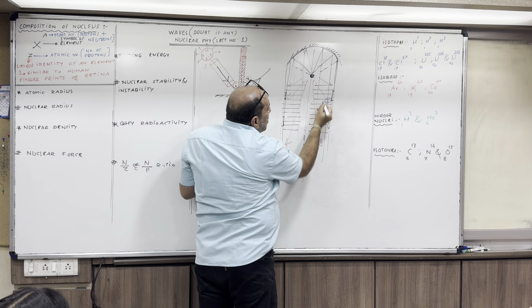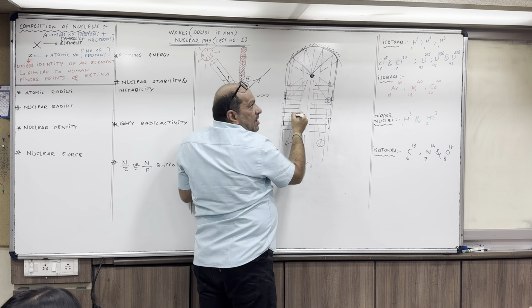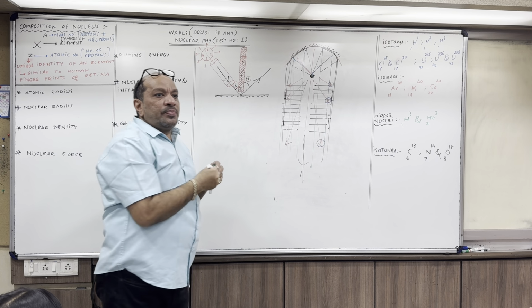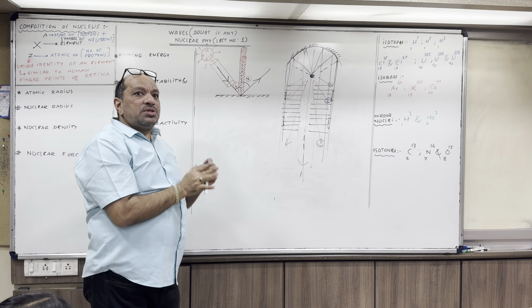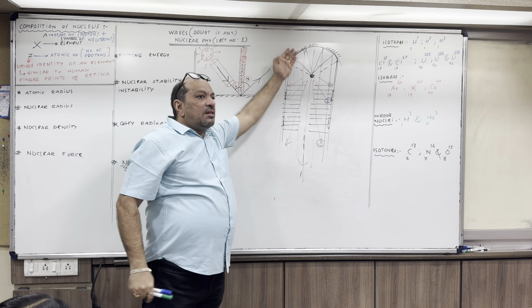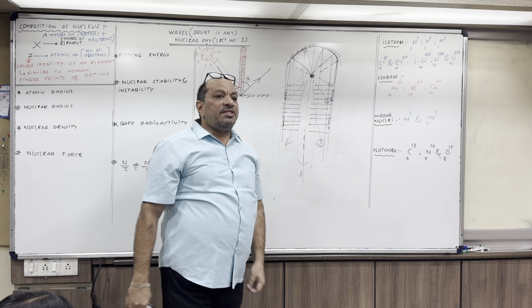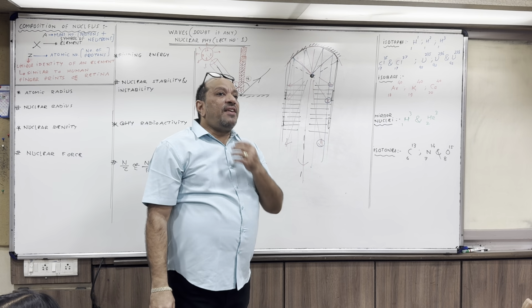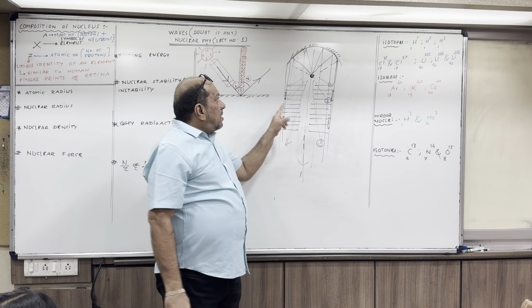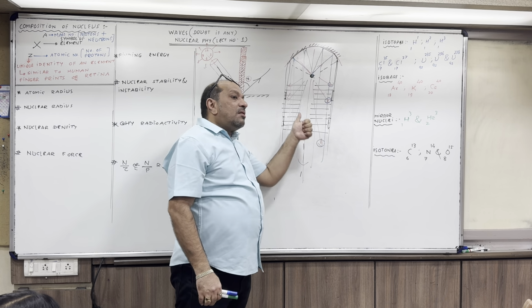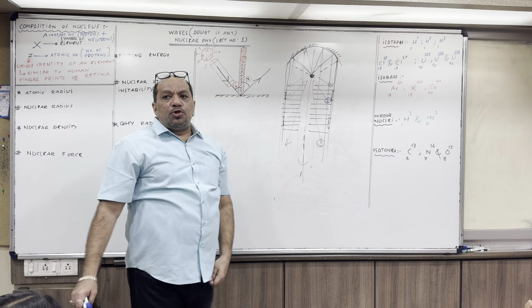It means you are getting the original direct sound, and you are getting the reflected sound also. No sound wave is wasted, and this particular length is kept less than 17 meters so that the echo effect is not there. Otherwise, if one sound wave comes from here and another reflects and comes from there, we will be getting a confused pattern.